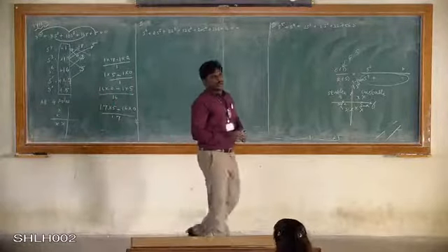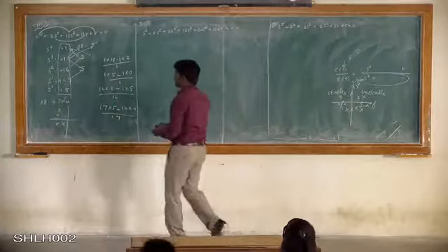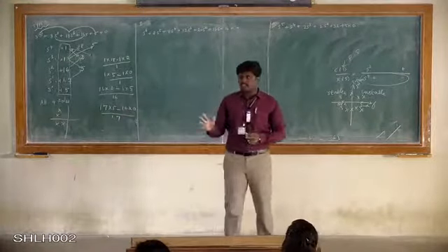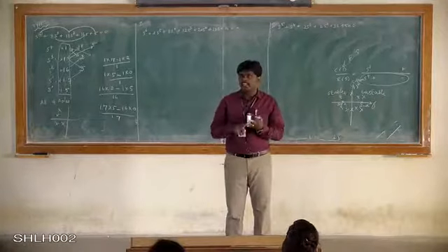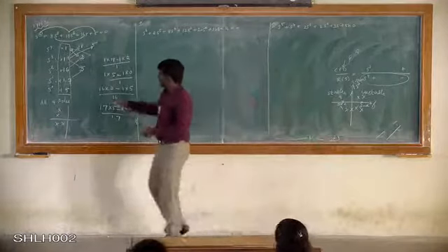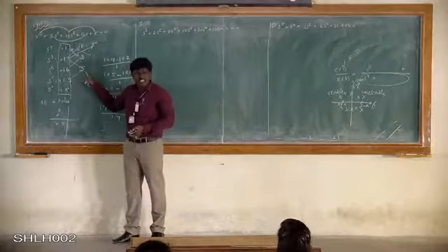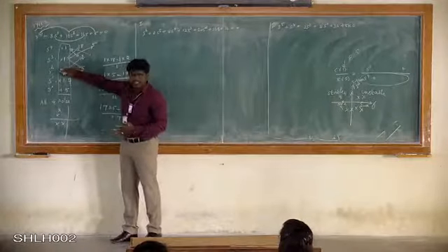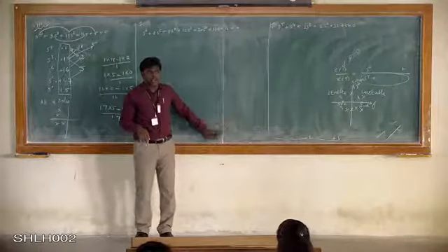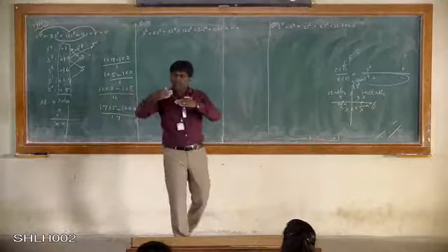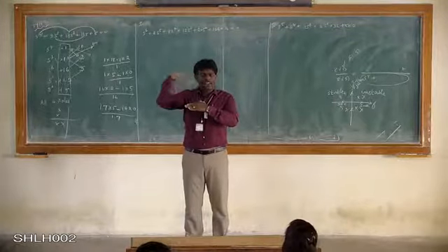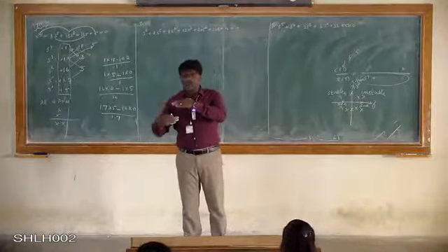Okay. So now, while we solve all these problems, we will be able to solve. This is type 1. While you make the Routh table itself, you will face 3 types. So this is another type. What would happen is that here we have got 2 elements, right? So instead of these 16 and 5 values, we will get 0, 0 over here. The whole row will become 0 in this particular problem, right? So if you get a whole row as 0, will you be able to get the next row value? No, because you are multiplying with those, right?